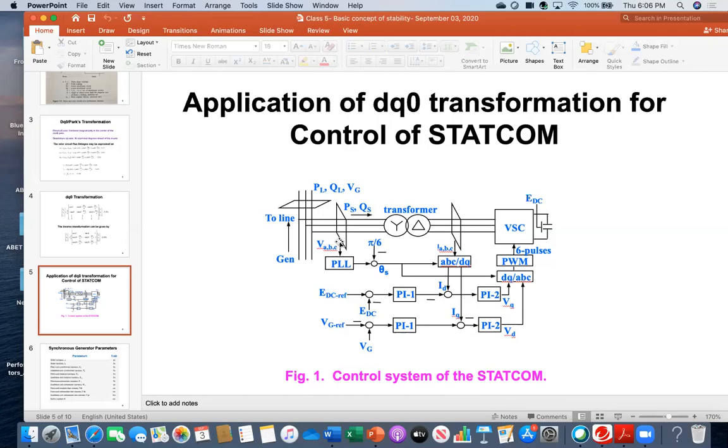And then it is given into the PLL, meaning phase locked loop, just to find out the phase information of those three-phase quantities. So this means that the PLL will give you the angle theta. But can you see it is added pi over 6. Pi over 6, how much is that? This is pi over 6, 30 degrees. Yes. Why is it used?